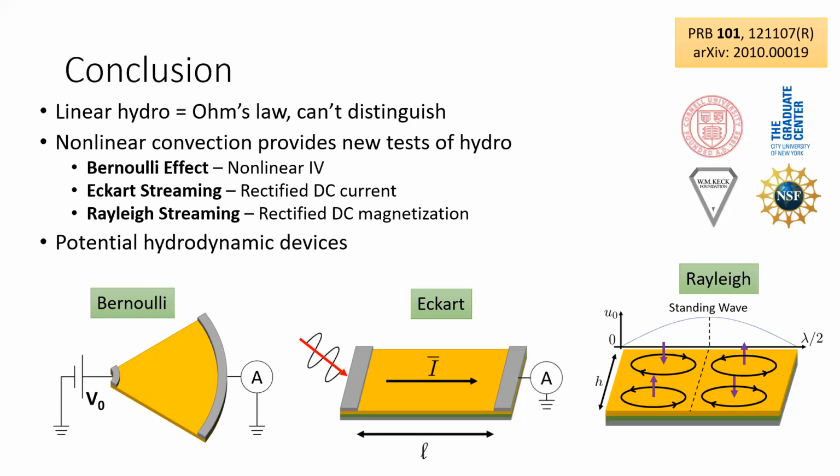I guess one thing is that the reason graphene was chosen as the model to do all of these estimates is that graphene has relatively low carrier density compared to the other devices, and as a result, it's easier to achieve higher Reynolds numbers in these devices without melting the device.